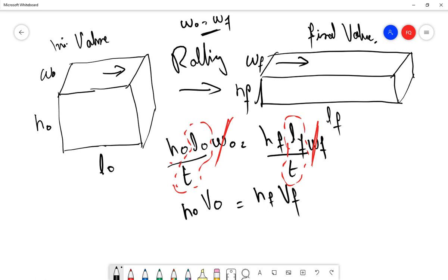It is easier to show it with the equations. So the velocity of this would be slower and velocity of this would be higher, because it has to quickly pass through the rollers and it has to slowly pass through the rollers. So what is happening here is that it was easier to show with this equation that this h naught is large and this hf is small.